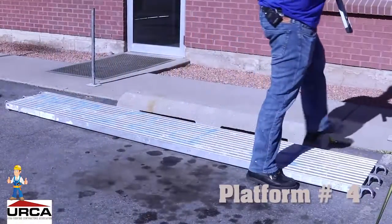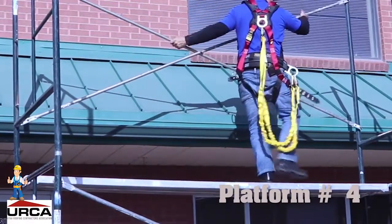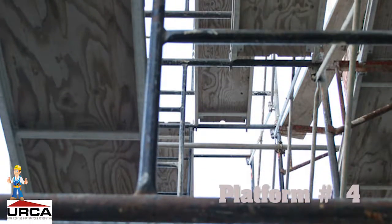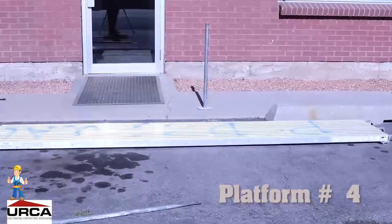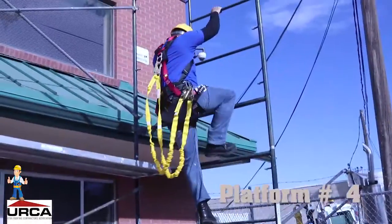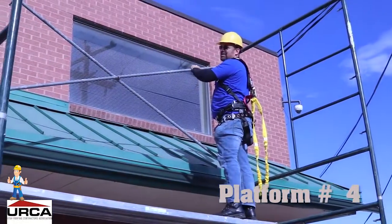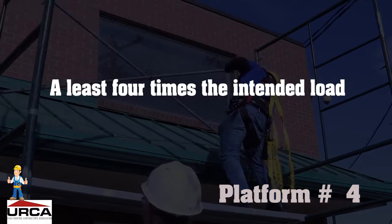Component number 4, platforms. Platforms are the working area of the scaffold, except when used as a walkway. Platform planks can be properly sized sawwood, prefabricated metal, or similar materials, as long as they are manufacturer approved for the task. Use only scaffold grade wood. Platforms must be fully decked and able to support without failure its own weight and that of the workers and at least 4 times the intended load.